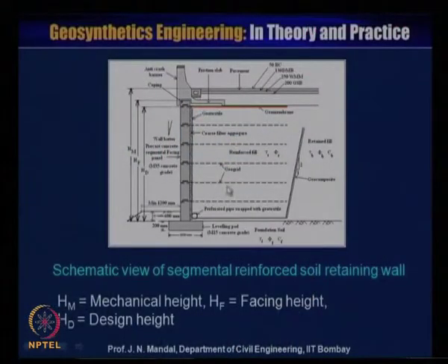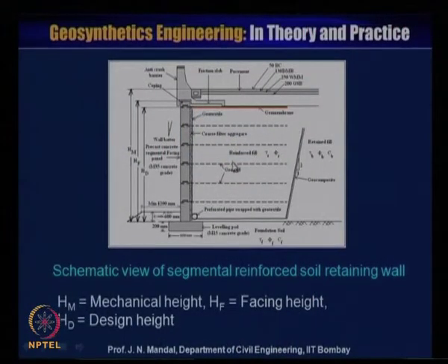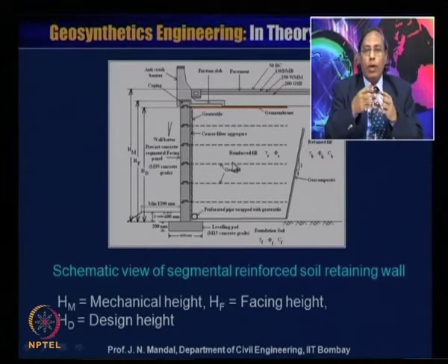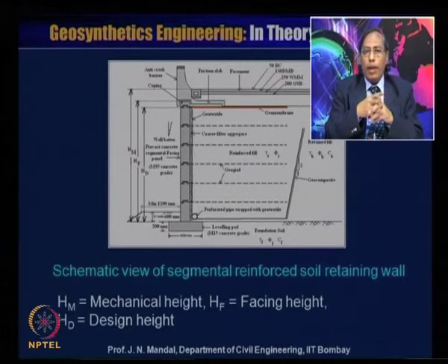Similarly, you should know the characteristics of the soil in the reinforced fill material: the unit weight of the soil in the reinforced soil zone, and the friction angle of the soil. And at the same time you require a proper kind of drainage system, and what kind of drainage system you should consider in your design.